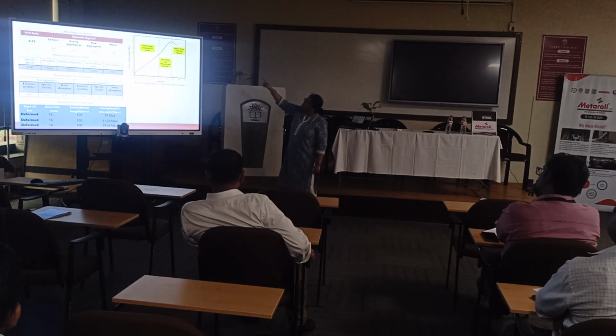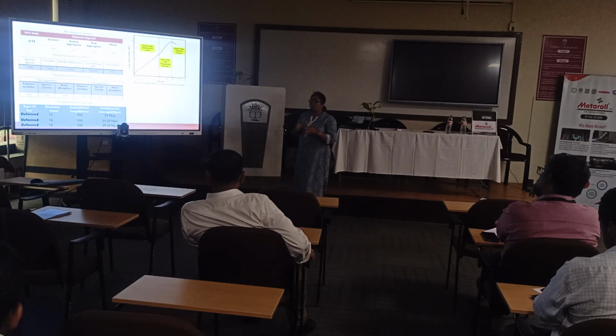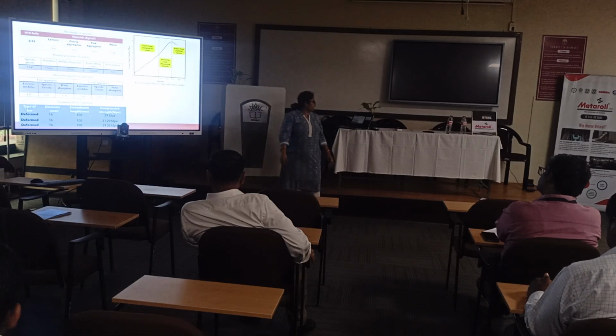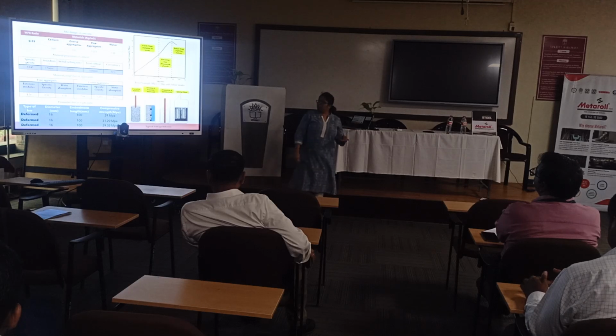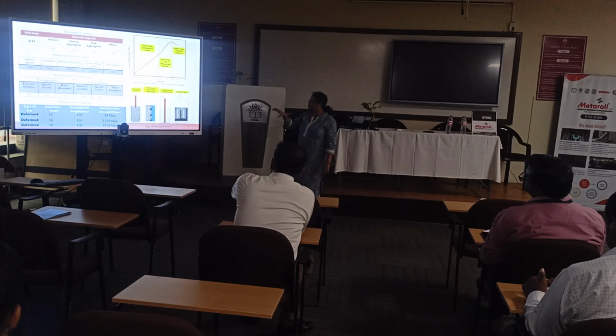The pre-peak behavior is very well seen in our machine, but the post-peak behavior is mostly not captured. Because it is strain control, after the concrete steel is pulled out, the machine suddenly stops. So the post-peak behavior is not well investigated, but for pre-peak behavior we got a large enough elastic range, which is good to be shown and utilized to understand the behavior of the specimens for bond strength.